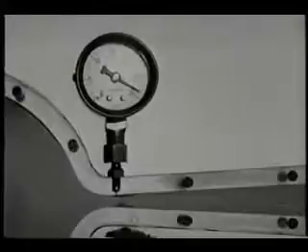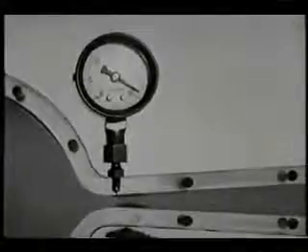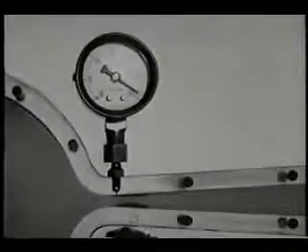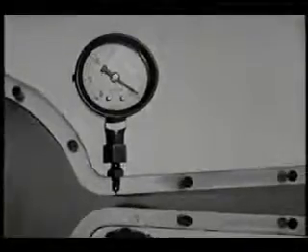The water changes to steam, and the subsequent collapse of the bubbles, which you can hear, creates enormous stresses in the wall. Mechanical stresses owing to the implosive collapse of cavitation bubbles on a surface do great damage to hydraulic machinery. And to marine propellers.